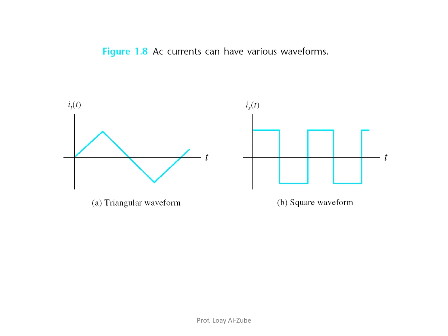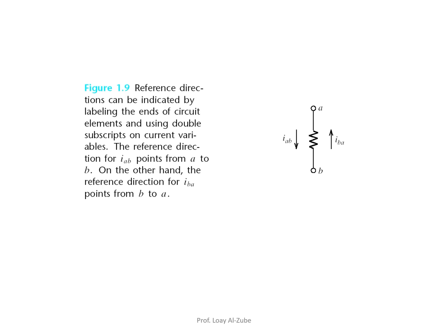In the lab, when we meet, you're going to be using the function generator to generate all these signals and look at them on the oscilloscope. Cool. It's a summary, so I'm going quickly with this, but I will slow down a bit later on. Now, if I told you that's IAB, that means the current is moving from A to B. If I told you it's IBA, it's moving from B to A. And that is the notion of how we are going to be using the symbols.